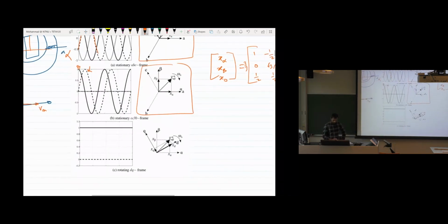And then later, we implement the PI controller. And the PI controllers work mainly with the DC component. So what we can do is have a DC signal instead of this sinusoidal signal. Now in alpha beta, here we still have the sinusoidal. In sinusoidal, they are varying all the time, so there is no fixed operating point. So in order to have a fixed operating point for the main analysis, we convert this into a DC component.